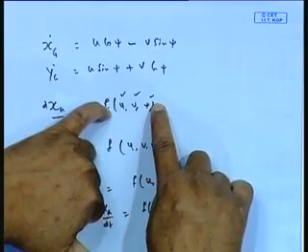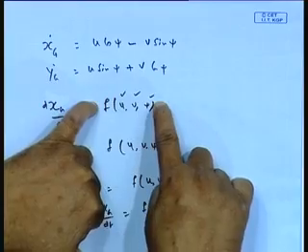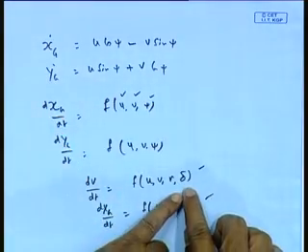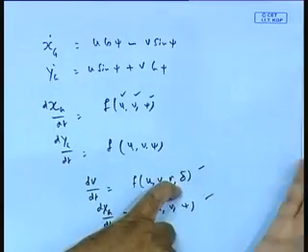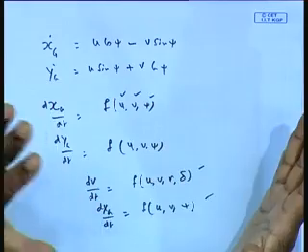What is important, of course, is that you have to fit the correct values here. These will be all function of hydrodynamic derivatives. Other derivatives, you will start with the t0. For example, the initiation is that at t0 my delta is given some small angle. You have just given a small angle. We have to also understand that in the equation of motion, for the surge equation, I have to also have thrust and resistance to be modeled properly.